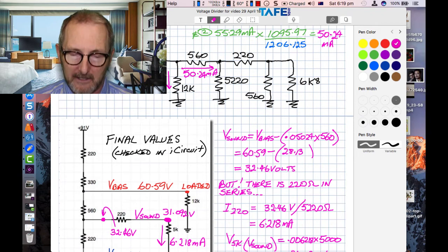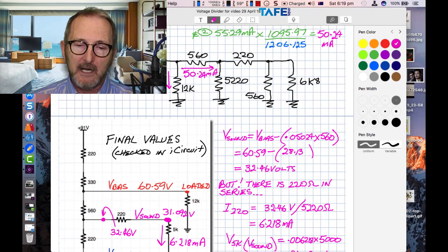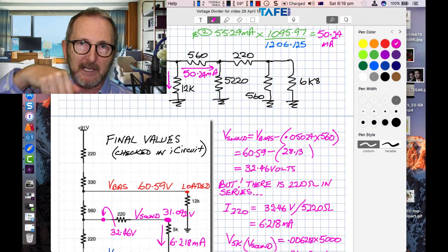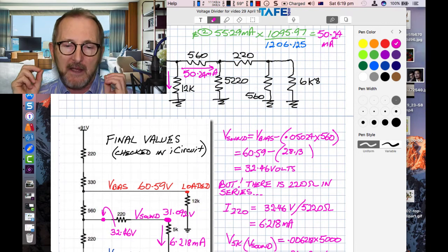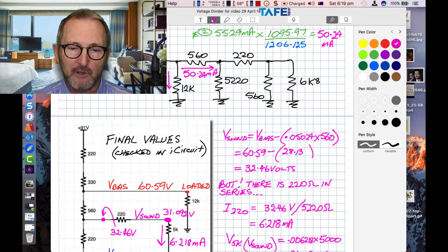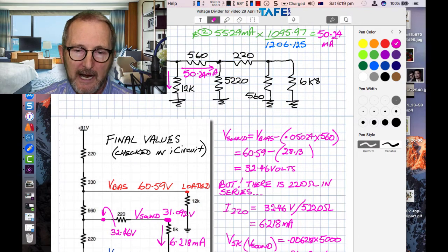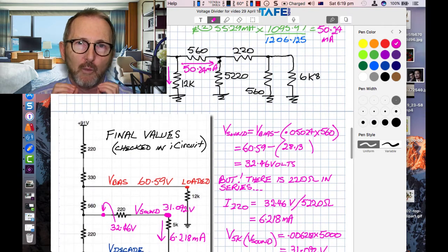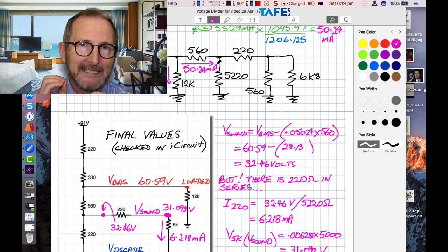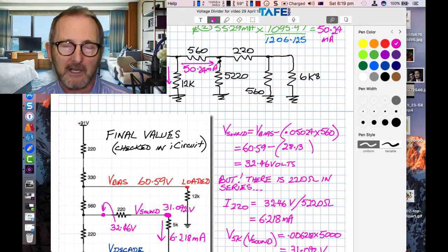this point here. Brilliant. So, let's just retrack, we had to use a current divider because we needed to find out that we had 5 milliamps going one way, we had 50.24 milliamps going the other way, and then we can use that 50.24 milliamps voltage drop across the 560 ohm resistor to give me the next node voltage. And that next node voltage becomes quite critical because we need to go ahead and do yet another current divider on that to continue getting the rest of the voltages and currents in the circuit.